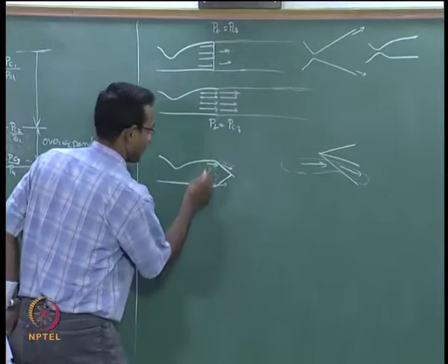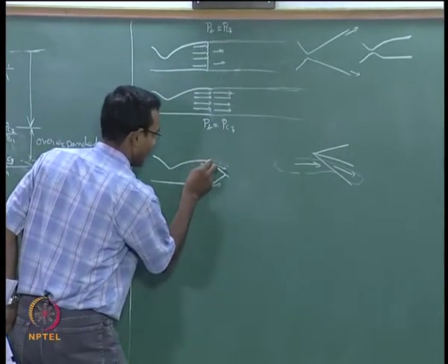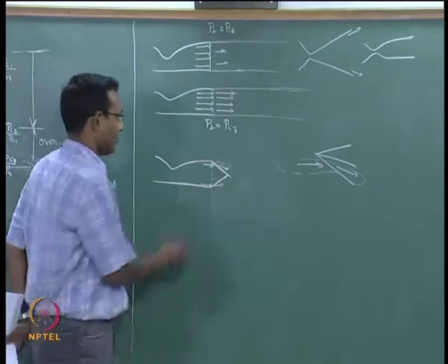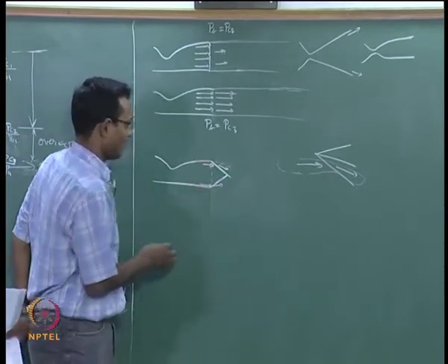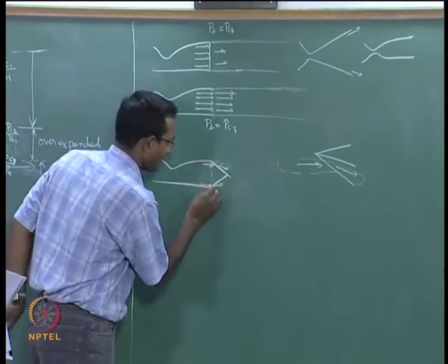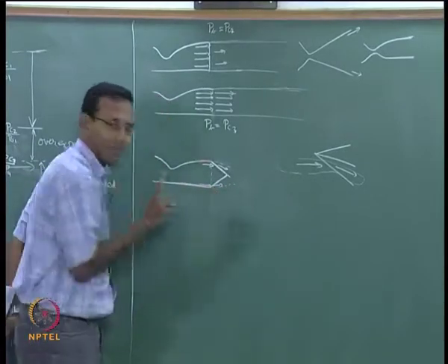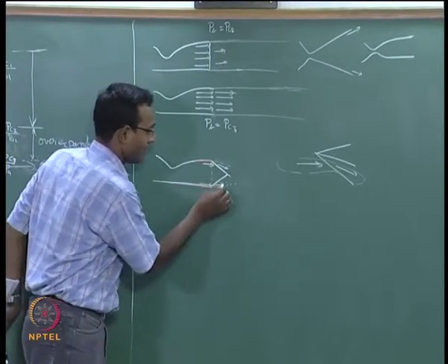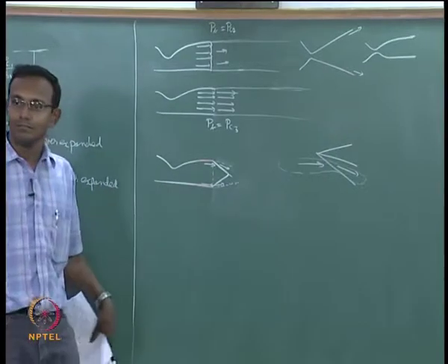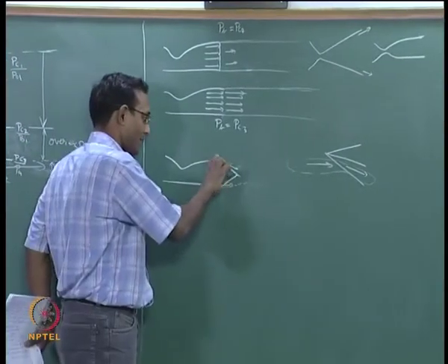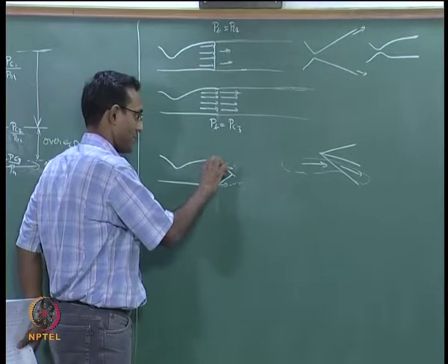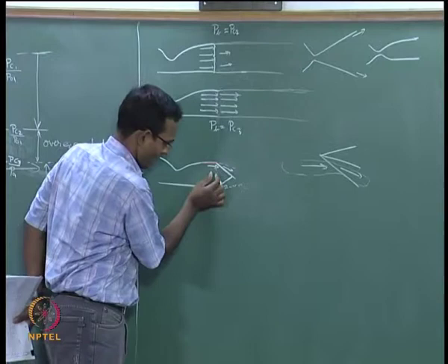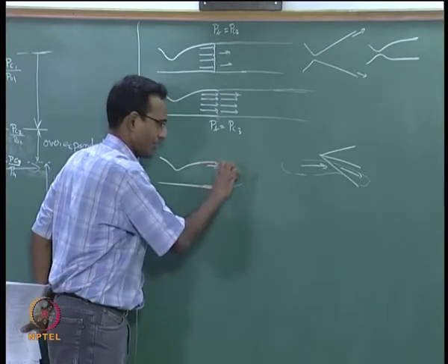Now that it is getting too confusing, I will draw this nozzle with red only near this portion. Okay. So this white thing is my shock, and so both the fluid elements are turned inward, which means my final streamline, the jet boundary, is going to be turning inward, right. What does that mean? I think of that jet as one slab of fluid here. That slab of fluid as it goes in is getting shrunk.